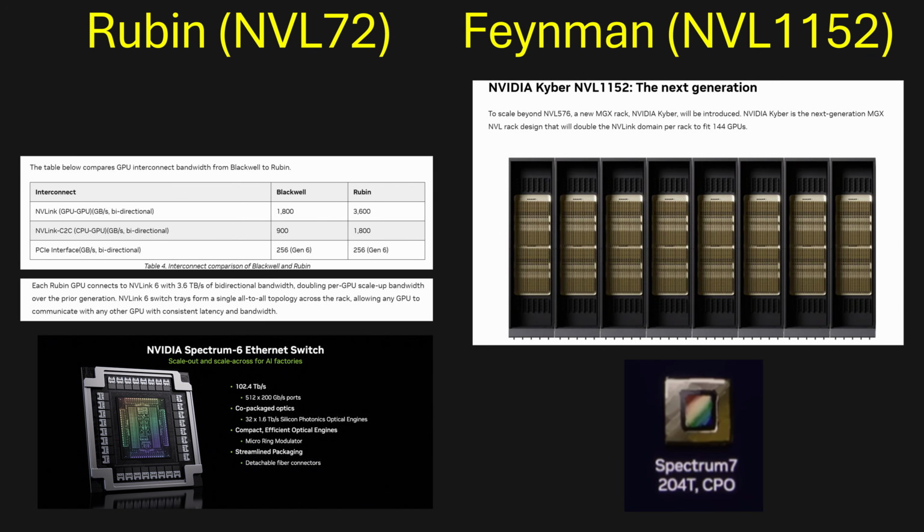Rubin, coming out later this year, will use the same number of copper NVLink lanes and still use PAM4 at the same baud rate, but it will operate each copper lane in full duplex, sending signals in both directions at the same time. This requires bidirectional SerDes and analog and/or digital self-cancellation of the transmitted signal on either end.